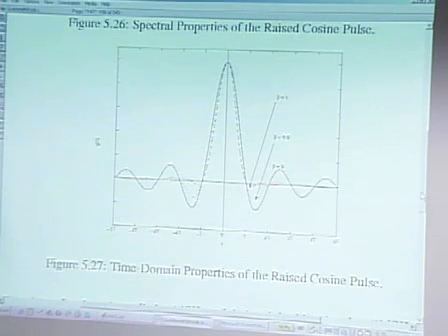And the windowing that's used, you don't just truncate this. You actually multiply it by a smooth window to progressively cut it off as opposed to abruptly. So you want to make everything smooth always. Otherwise, the frequency shape gets very distorted.